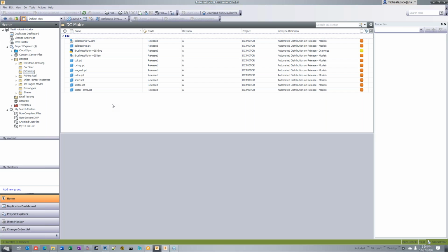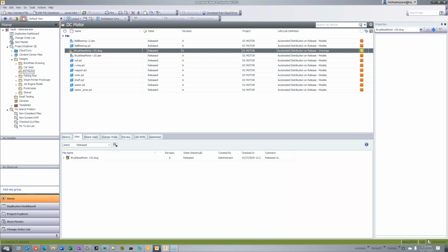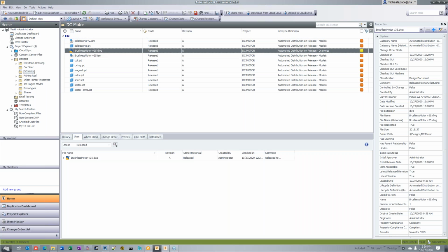There is also another method, and I won't get into it too far, but you can go in and create a tool, or I should say a check, in the vault that would tell on this drawing life cycle to make sure that we synchronize all properties and update views or update things. We could set that up to make sure that the title blocks are updated with the correct iProperty fields before publishing. It would be a little bit more complicated because we're running a pre-publishing task, but yes, we could still do that.